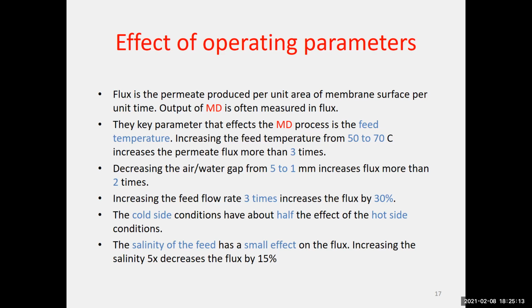One of the good things about the membrane distillation technology is that it is tolerant. It can handle high salinity. That's why in some applications, and one of the projects that we have, we use the high salinity brine leaving a normal desalination technology and take it as an input for a membrane distillation technology, so that it can handle higher salinity. And then you have more recovery of sweet water out of the salty water that you would have.